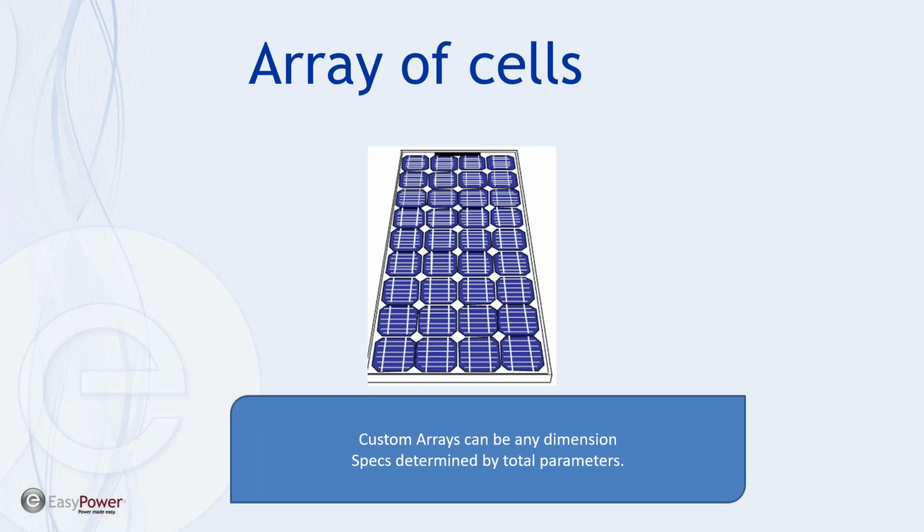So first of all, probably one of the strengths, as far as I'm concerned, with the EasyPower methodology is the lack of need to deal with the manufacturer's name, serial number, or part number, because as we do in AC elements, we look at the construction and the basic electrical theory, if you will, behind a piece of equipment. So what we do is model the array rather than an individual model or panel.